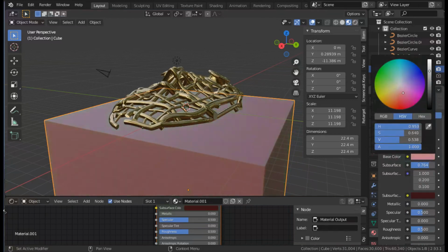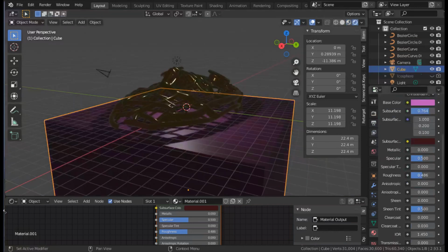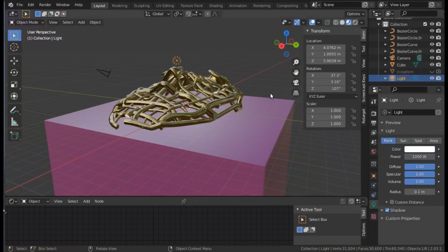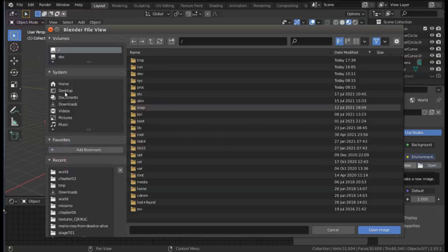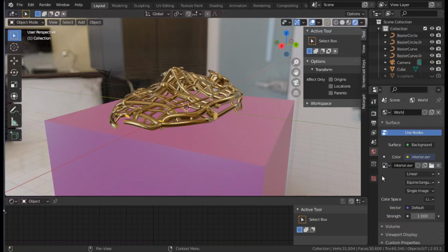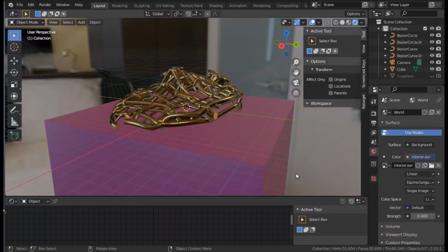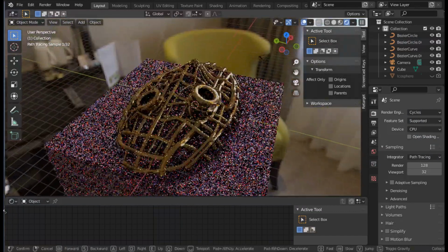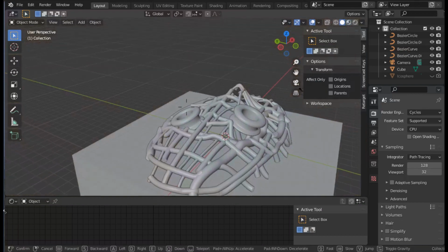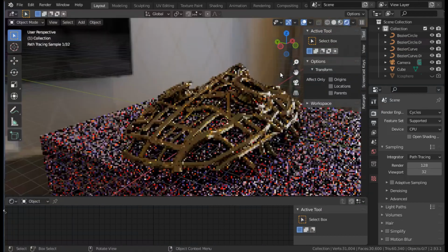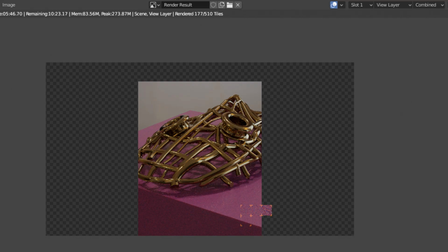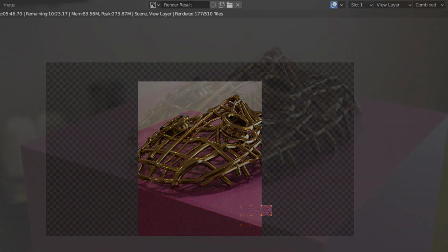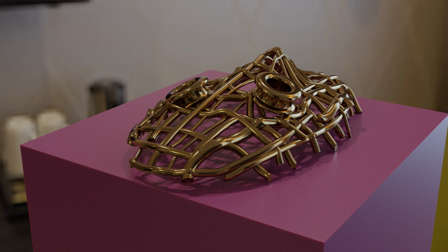We're going to render it using Cycles, so we'll put Cycles as the render engine. For the lighting and for the background, we're going to use an environment texture. Go into the World Properties tab, and then under Background Colour, select Environment Texture, and then browse to the installation folder where Blender is. Navigate down to Data Files, Studio Lights, World, and we'll select a suitable interior texture.